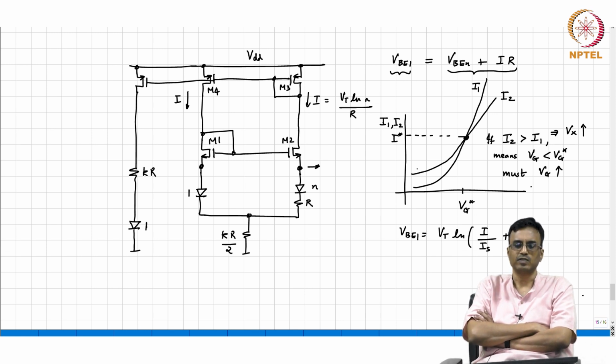All right, and you've seen a similar situation earlier. What is that? Yeah, fixed GM bias also had the same problem, right? If you didn't know how the circuit came about, it's very easy to flip the mirror orientation, and then end up with a circuit that doesn't work.